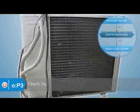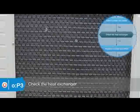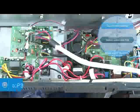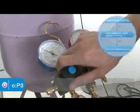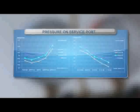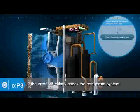If the fan is normal, check whether the heat exchanger is dirty. If yes, clean the heat exchanger. If the error still exists, replace the outdoor main PCB. Please refer to the table to check whether the system pressure is too high. If yes, recycle the overcharged refrigerant. If the error still exists, check whether the refrigeration system is okay. Find out the cause and solve troubles.